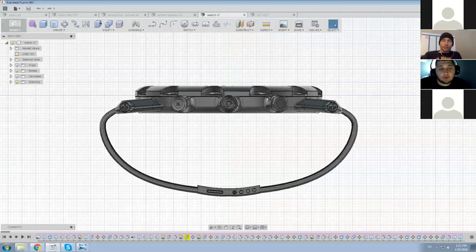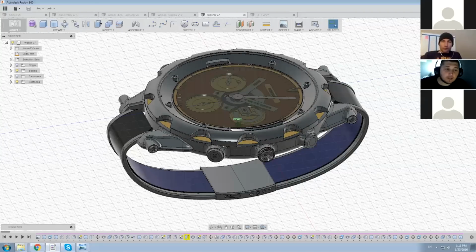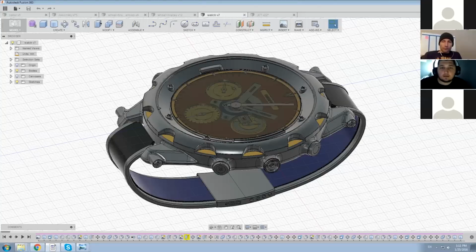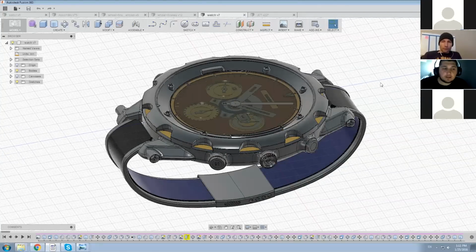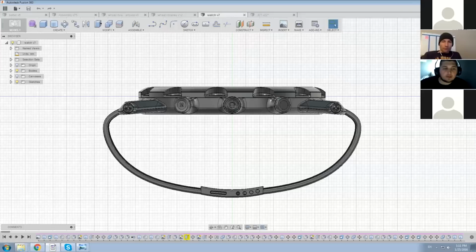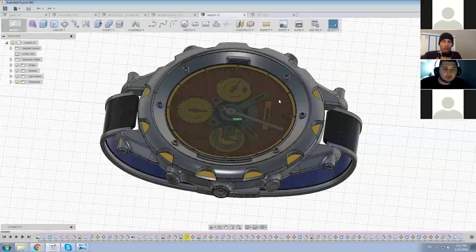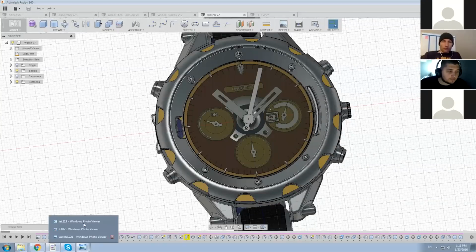The huge benefit of modeling in CAD and rendering in Keyshot is that it's not polygons. So it's basically unlimited zoom in, very smooth lines, no tessellation. If you're only an illustrator, or basically a concept artist like me, you don't have to worry about polygons and how the geometry or the mesh looks. In this case, you get amazing results from Keyshot.